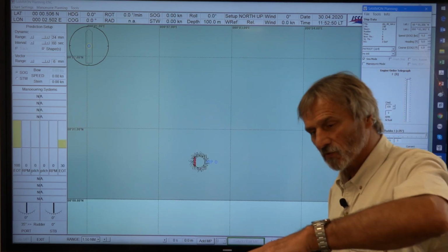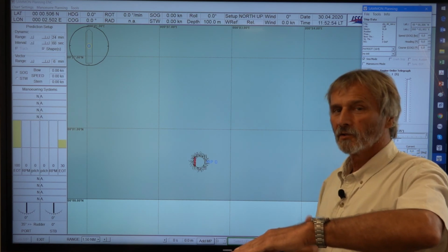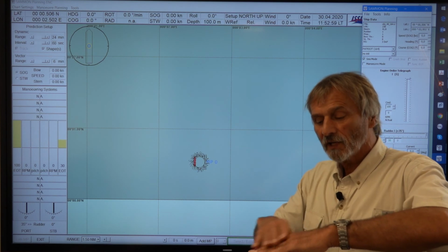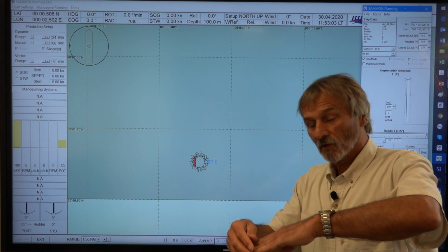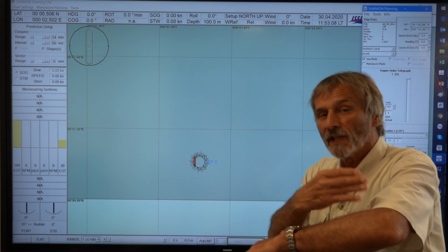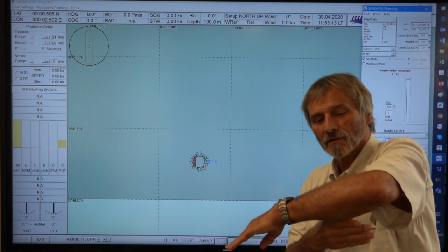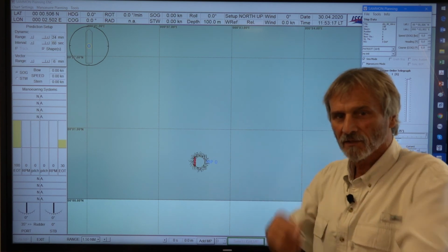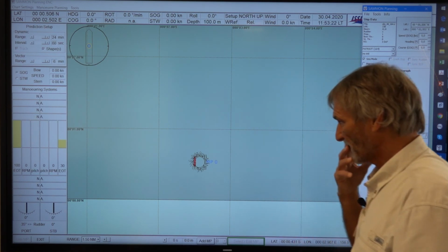So if the ship is trimmed to the bow, then the turning circle is smaller. You can imagine why, because the drift forces are really attacking the ship on the bow, and so it's nicely turning, and the damping forces at the stern, because the stern is going out of the water, are reduced. So the unstable moment wins, and the ship turning circle is much smaller.